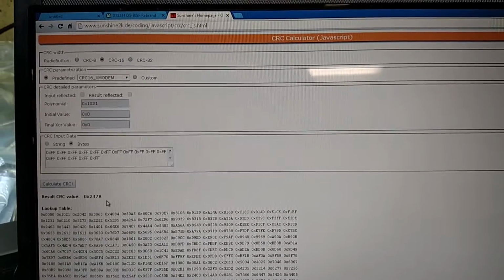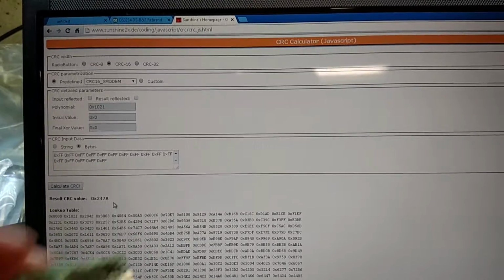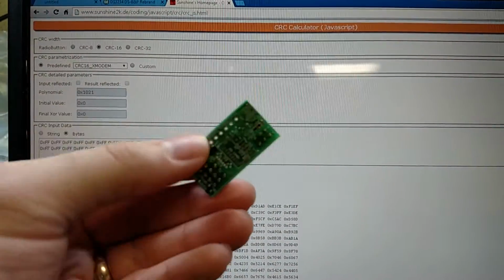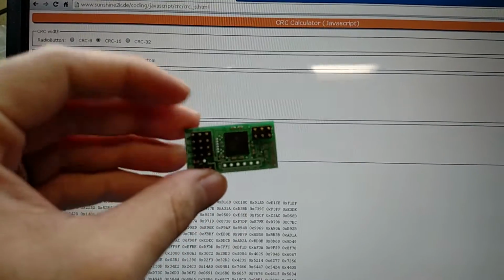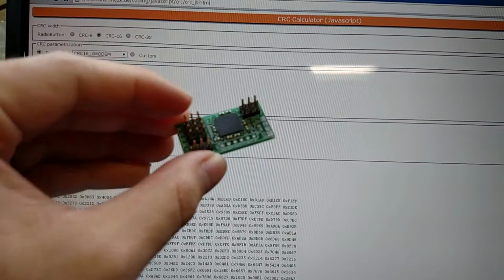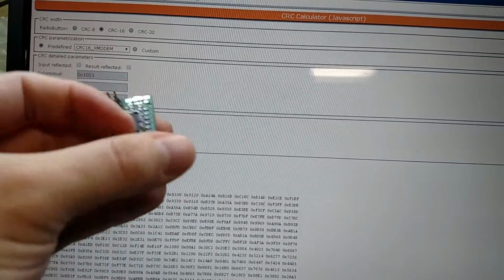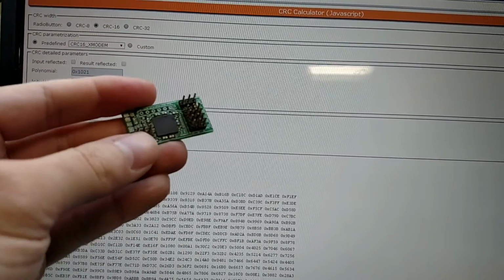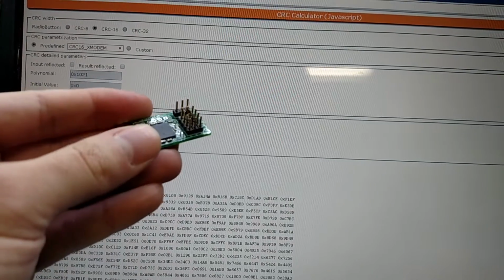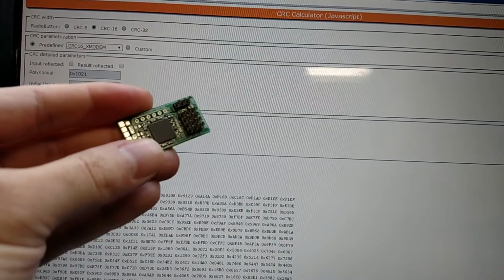And for hardware, I'm thinking about using my little motion controller and just do a little bit of SPI with it and have it read out the flash memory chip, modify that byte, calculate a new checksum, and then write it back.